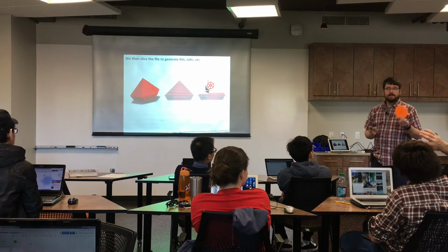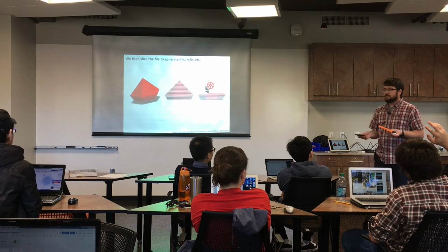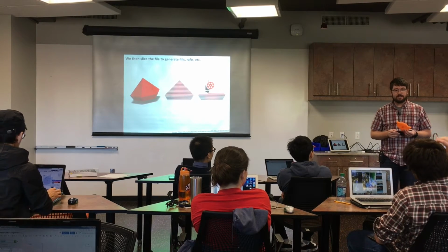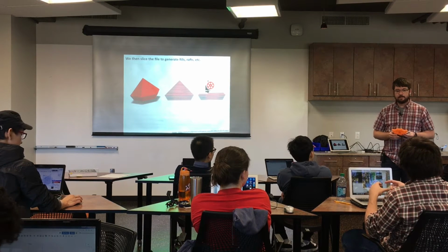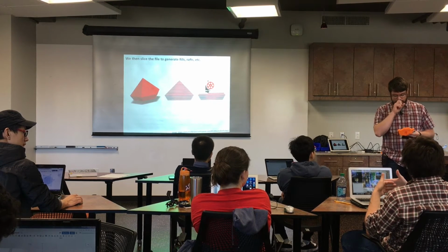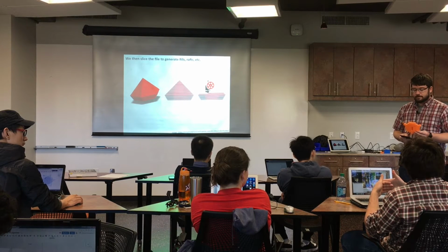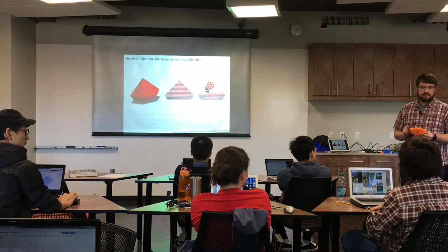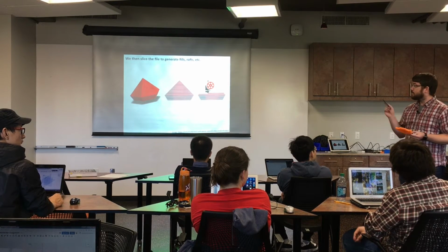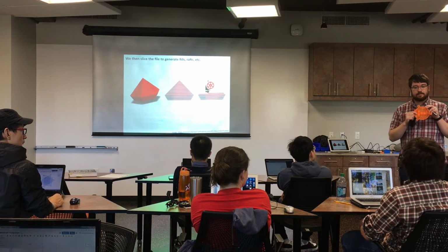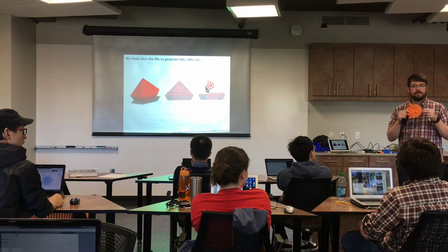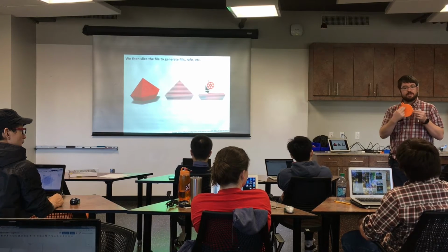And the plastic isn't that expensive, but it's best to not use it, wear on your machine and all that. How thick does it need to be before you have to specify that you're going to switch to a honeycomb structure? Because I'm assuming if you have a thin, semi-thin wall, it's going to be solid, but... Yeah, so there's a wall thickness parameter that you can adjust in your slicer. So you can see here, I think I have my wall thickness set at like 2 millimeters. So anything that was over 2 millimeters, it started shelling it out.